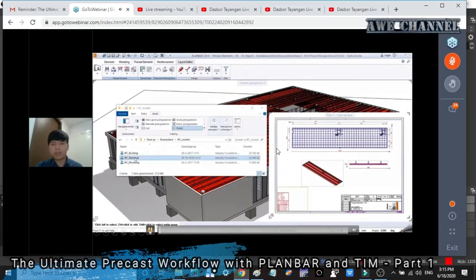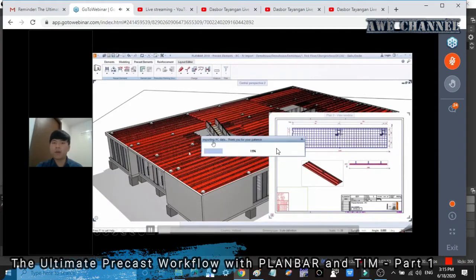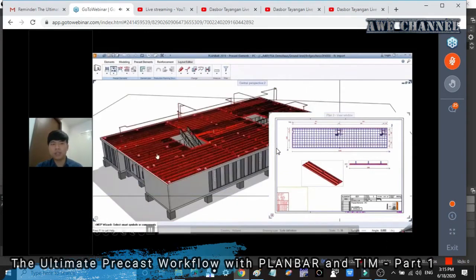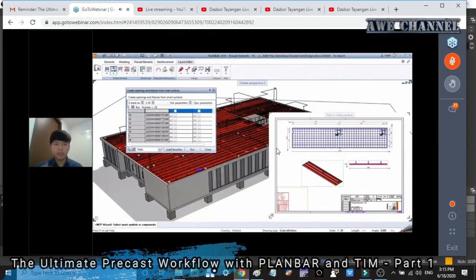This is maybe a sneak preview of how we import IFC data into our precast model. You can see we just drag the MEP model into this file, and we can select what kind of openings we want through this very simple list. Right, then you load these fixtures or installations on this precast model, and all this will be done automatically in a very short period of time. This whole video is around 1 minute, and we can import the MEP model, create openings and fixtures, then create a shop drawing directly from this. And what's more, we can use the data to send to machineries for production.